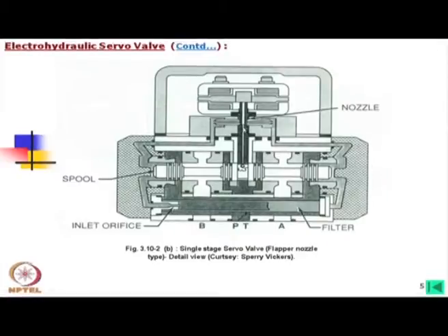This is the flapper and this is the spring, and then this is the armature torque arm, and essentially a filter is always used. So, flow is going through these filters. Now, this filter is an additional filter. Apart from this there will be another filter which is called the high pressure filter. This is connected in the line from where the flow is coming to this system.